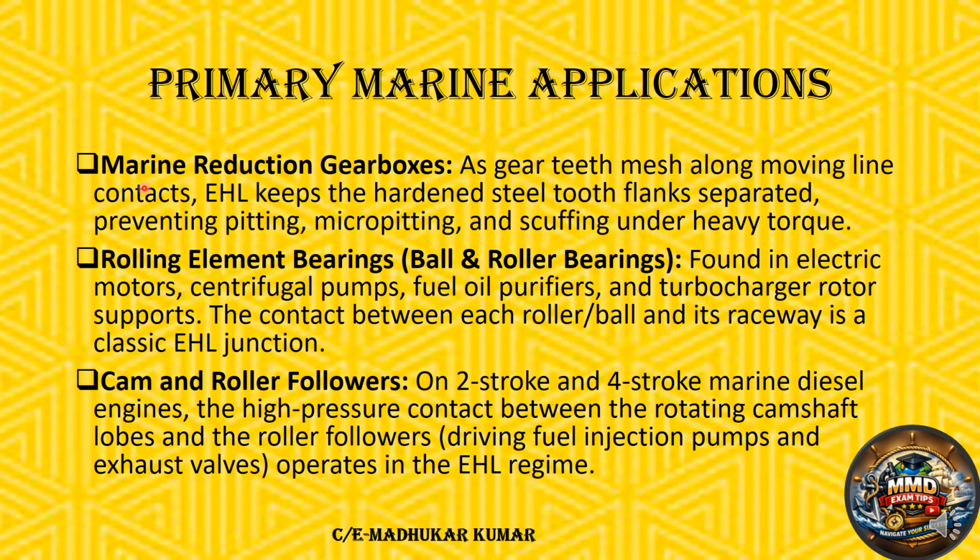Marine applications: marine reduction gearboxes, rolling element bearings, ball and roller bearings, cam and roller followers. How is it in gearboxes? As the gear teeth mesh along a moving line, elastohydrodynamic lubrication keeps the hardened steel teeth flanks separated, preventing pitting, micro pitting and scuffing under heavy torque. As we have seen, in the gearboxes the gear trains are there, the motion happens between them, and due to this elastohydrodynamic lubrication is possible.